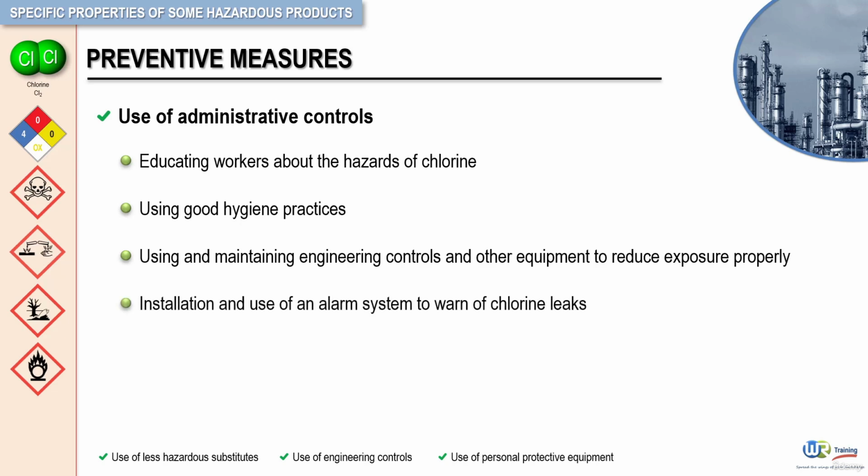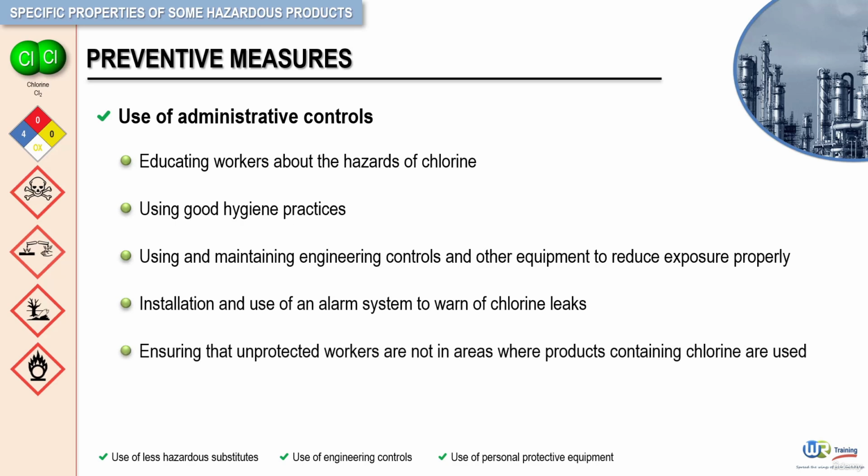Installation and use of an alarm system to warn of chlorine leaks. Ensuring that unprotected workers are not in areas where products containing chlorine are used. And cleanup of spills quickly and properly using appropriate protective equipment and clothing.